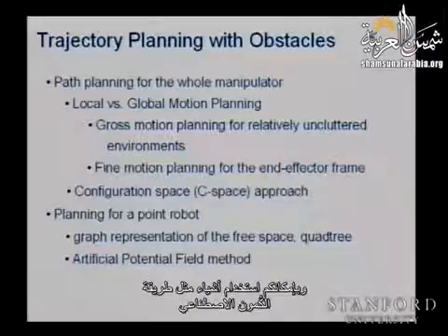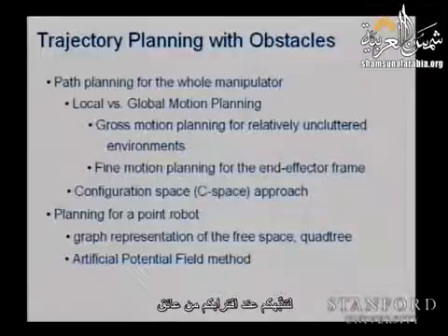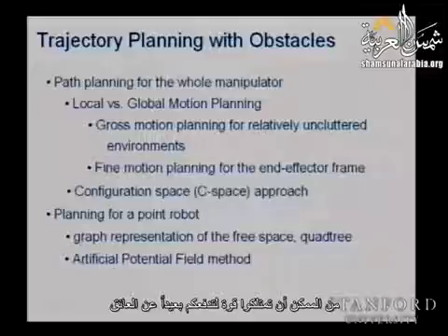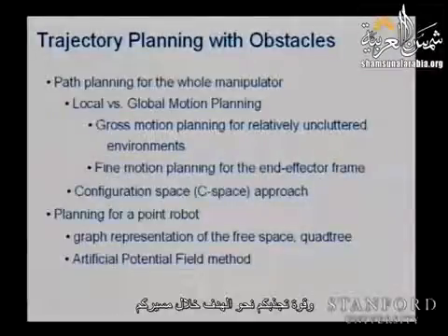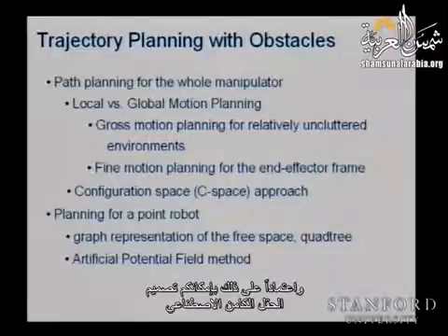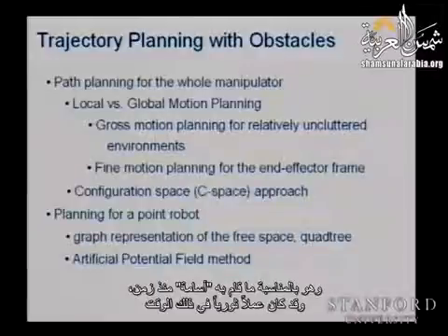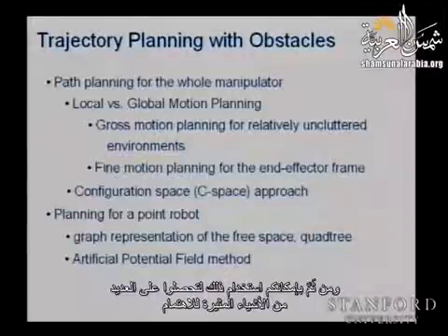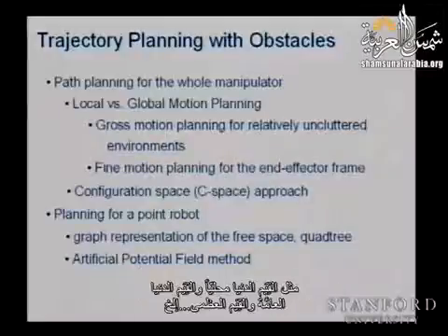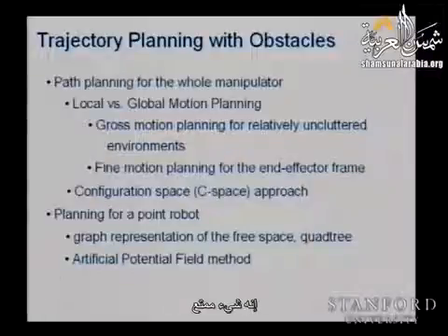You can also use things like the artificial potential method: as you go closer to an obstacle, a force repulses you from the obstacle, and a force attracts you to the goal, and based on that you build an artificial potential field, which is, by the way, what Osama did way back in his thesis. It was very revolutionary work at that time, and you get into all kinds of interesting things like local minima, global minima, maxima, etc. So it's a fun thing.